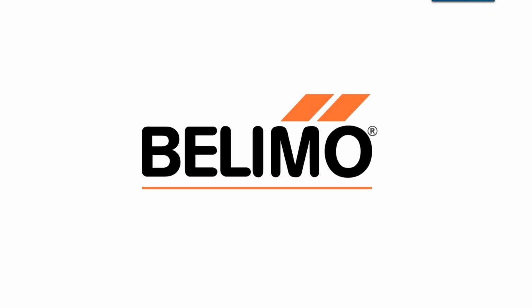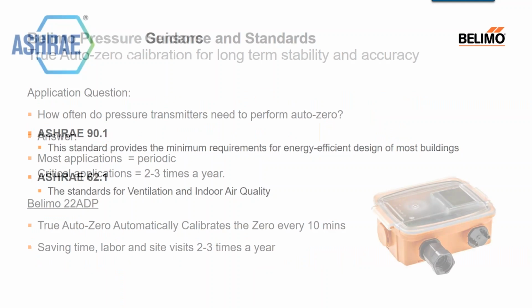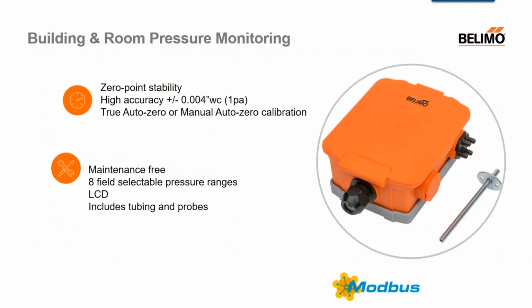Sure. How accurate are the air differential pressure sensors? Air differential pressure. We have 3 ranges. I think I can go back to the slide. Here we have 3 models for the air pressure. We have a 0 to 1 inch range, which has 8 selectable ranges in, and the accuracy of all those 8 ranges is plus or minus 0.004 inches water column.